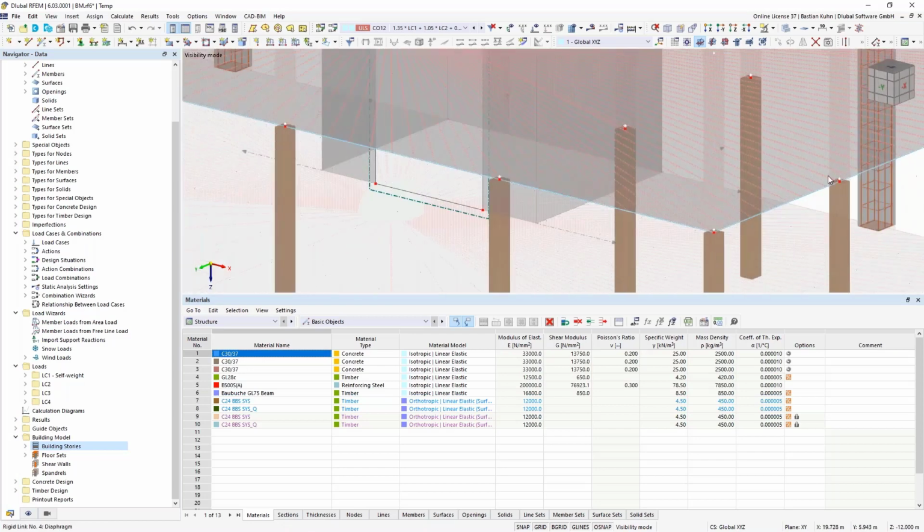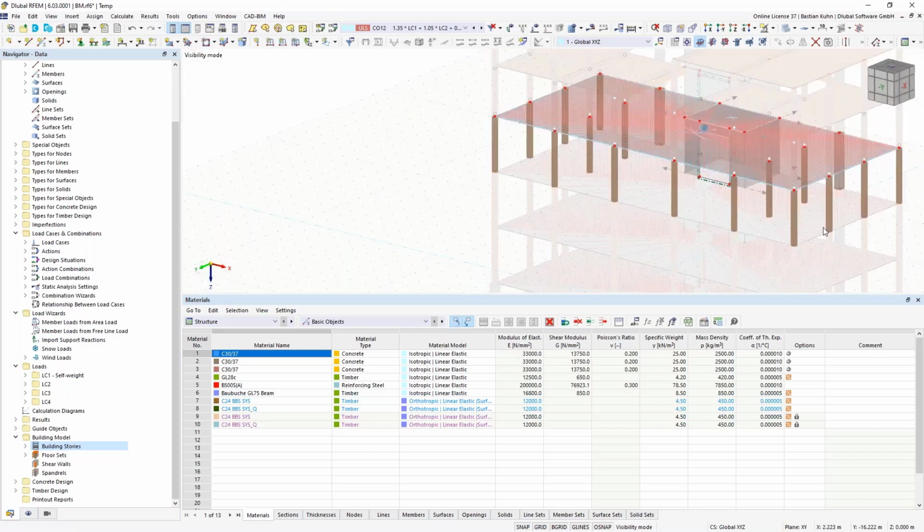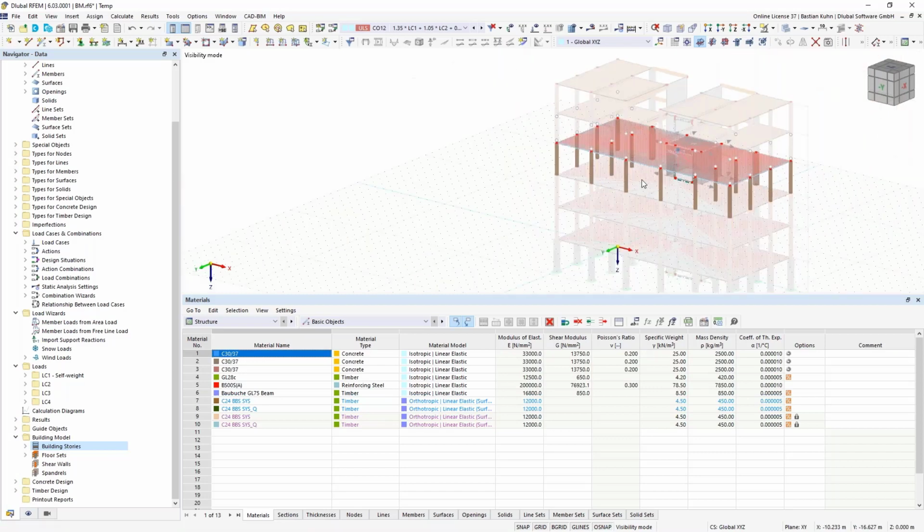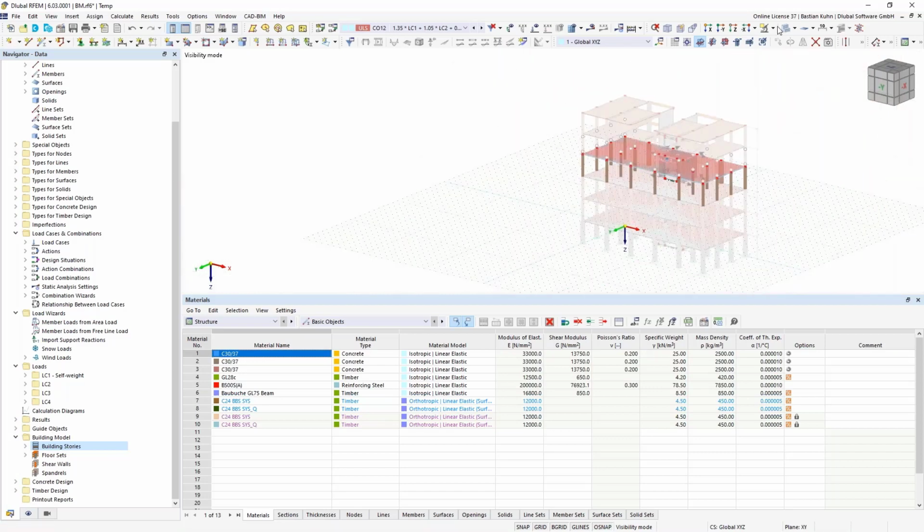Not completely rigid, as the ends of these rigid couplings have a moment hinge, and that's also the reason why I did not define moment hinges on the columns in here, as the ceiling itself is considered as a ceiling. It may sound a little bit stupid, but that's an important point. Yeah, that's the first change that we have from this.